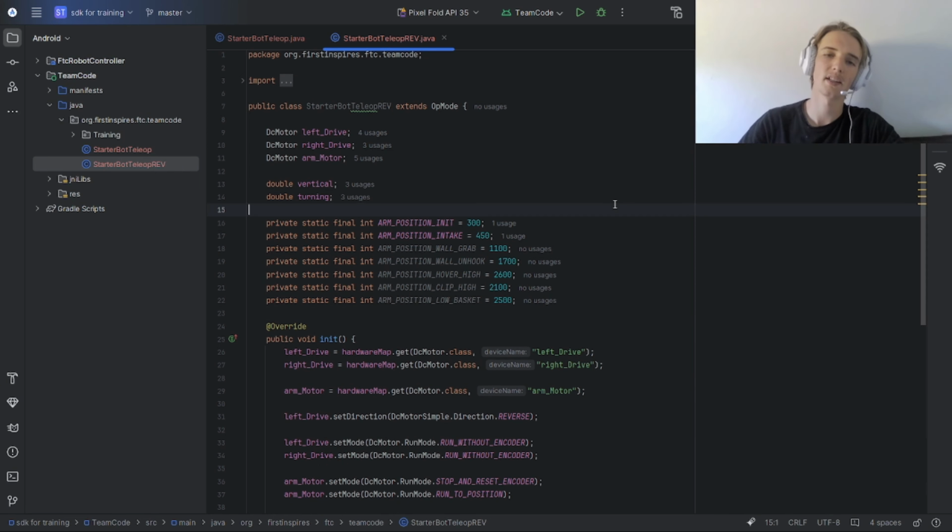You don't need to do anything with the drivetrain code because we are not using the encoders. It's just a set power of the motor. The right and the left motors will be the same. The left still needs to be reversed. And again, you just have to make sure you've got it plugged into the right ports. The only things that would change don't have to happen in the code. Your code's still going to control the drivetrain the same way. The motors might just go at slightly different speeds, which means the drivetrain drives slightly faster or slower. I'm not sure which way around it is. But you don't actually need to change anything in the code for that.